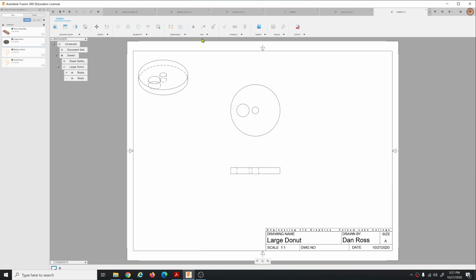Then throw some dimensions on there. So let's see, where are they? Here they are. Do a diameter, throw the diameters on, click that. It's really pretty, super easy. Yeah, so here, there's a clearance on this, right? It's 0.27, which is fine. And the peg coming out of the base is 0.25.